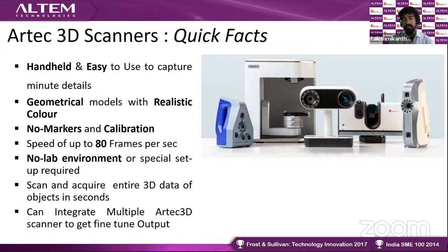Other than that, we can also use it for inspection, like once the part is manufactured, once your design is ready, and before you go for integrating with other existing components, you can validate it in a computer coordinate system. And then, as I said, with the long range terrestrial scanners, there are different kinds of applications. And I forgot to mention that one of the major disadvantages of lidar based scanners is that the cost is too high.